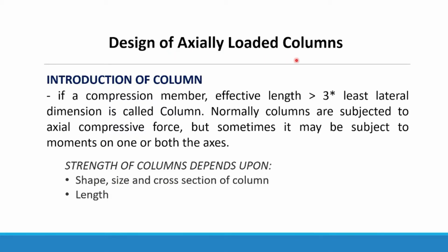Design of axially loaded columns. Introduction of column. If a compression member's effective length is greater than 3 times its least lateral dimension, that is called a column. Normal columns are subjected to axial compressive force, but sometimes they may be subject to moments on one or both axes.